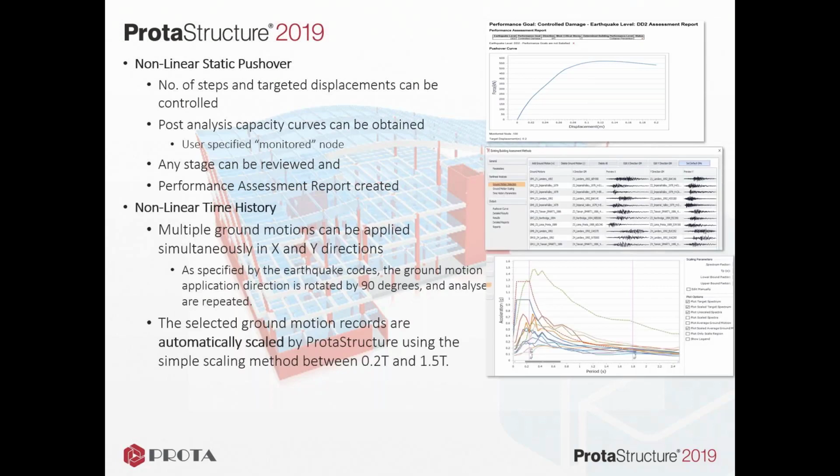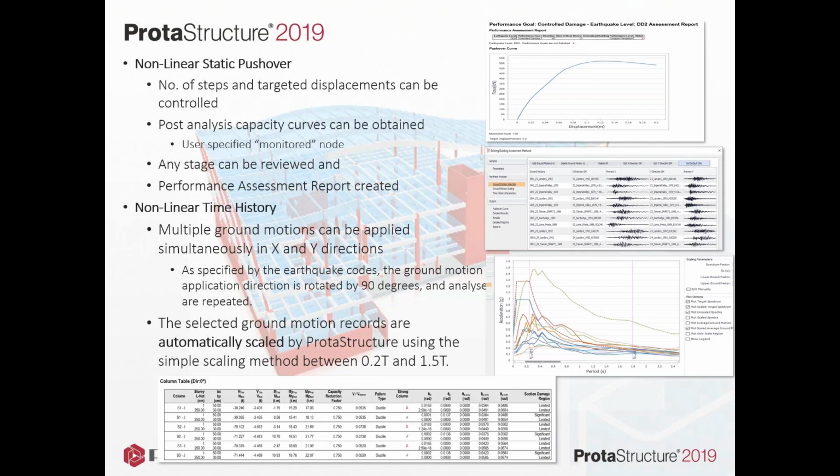For nonlinear analysis, the interesting thing that we do is that you can load different earthquake events from around the world, and we will automatically scale these for you. So depending on the code requirements, maybe you're using 7 or maybe 11 different events, we will automatically scale these against your required response spectral curve for design. Okay, and we will look simultaneously in different directions at these as well. And we will also assess this against code requirements.